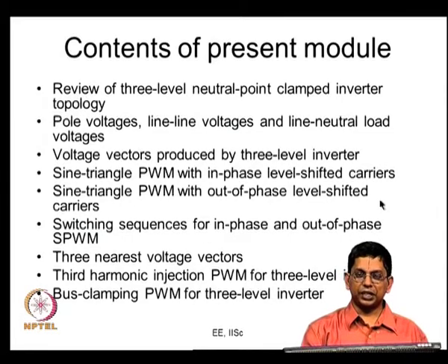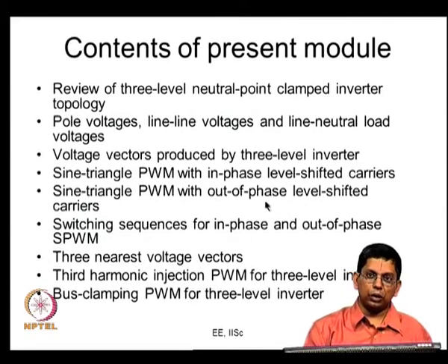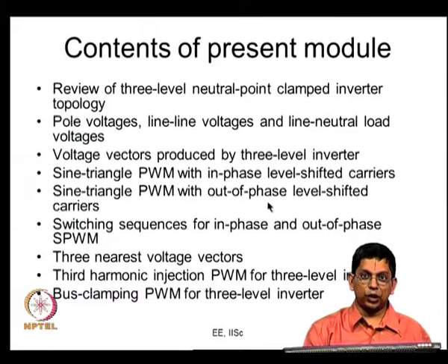So, these 2 level shifted carriers, and again it is not necessary that they have to be in phase, they could have some phase difference also. So, we looked at this in phase and the out of phase issues now. This comes because such a thing is not there in a 2 level inverter, where you use a single carrier only.